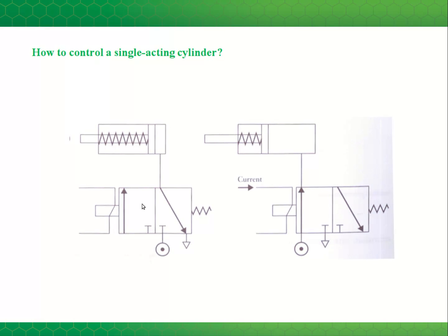Quick question, what is the designation for this valve? So how many ports does it have? 1, 2, 3 ports. And how many positions? 1 position and 2 positions. So there are 3 connections to the valve, 3 ports, and there are 2 boxes, so 2 positions.